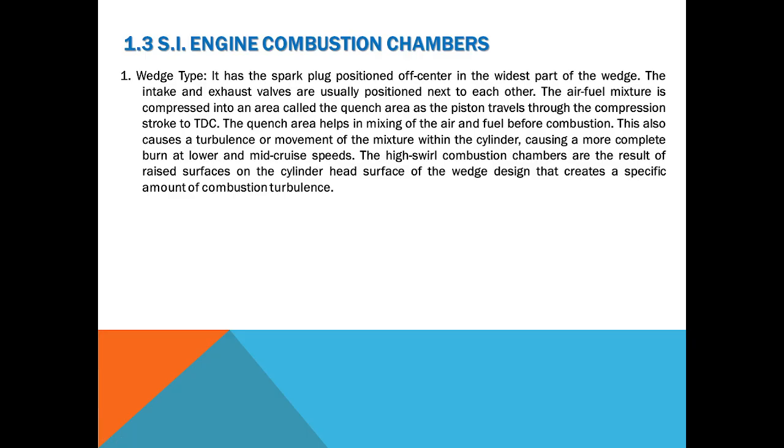In the wedge type, the spark plug position is off center in the widest part of the wedge. The intake and exhaust valves are usually positioned next to each other. The air-fuel mixture is compressed into an area called the quench area as the piston travels through the compression stroke to top dead center. The quench area helps in mixing the air and fuel before the combustion.